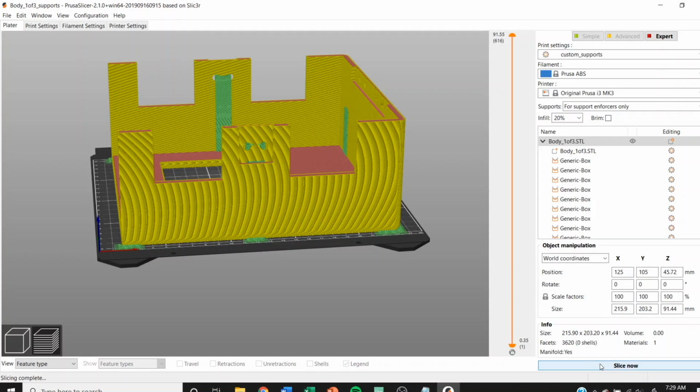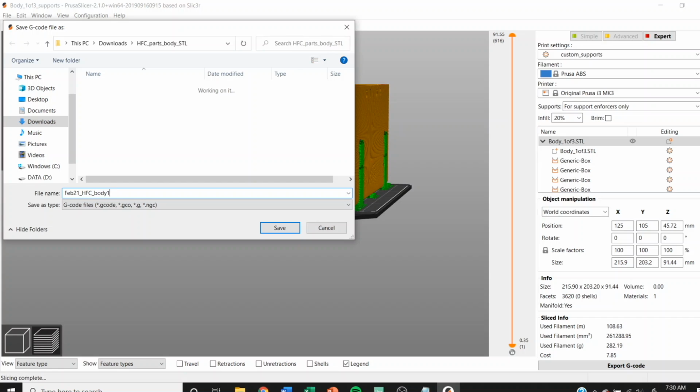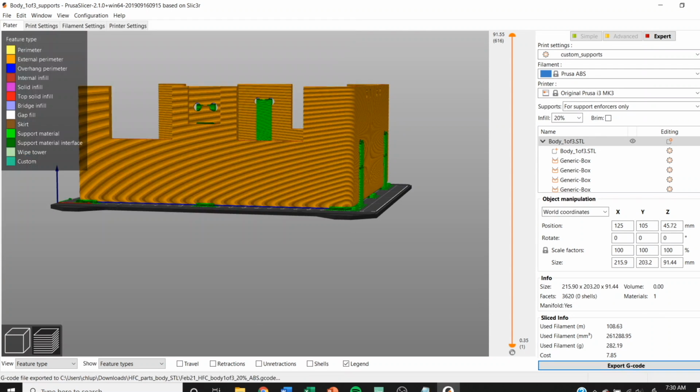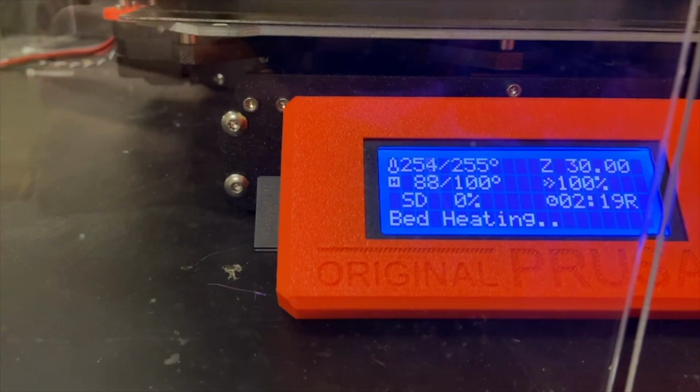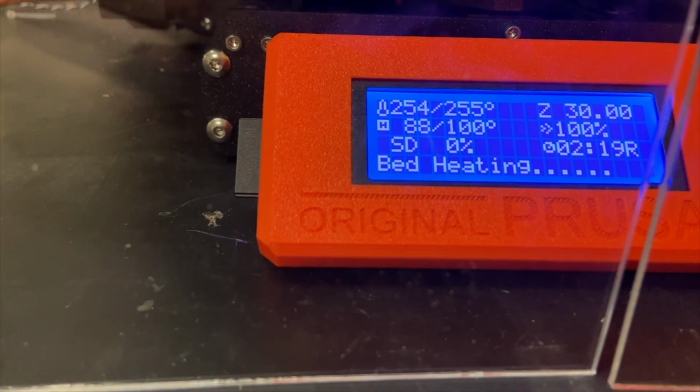Yep, and now turning the skirt height to 0, we don't have that toolpath error, although I would always recommend that you try to print only small to medium things to avoid that sort of error and to increase precision. And when you're happy with the supports that you have, I prefer to save the G code with a date so that if you're making incremental improvements on the design. This is a Prusa i3, and we use a Prusa slicer, so everything is obviously compatible.